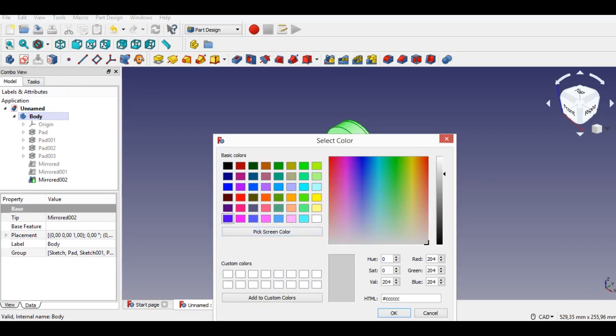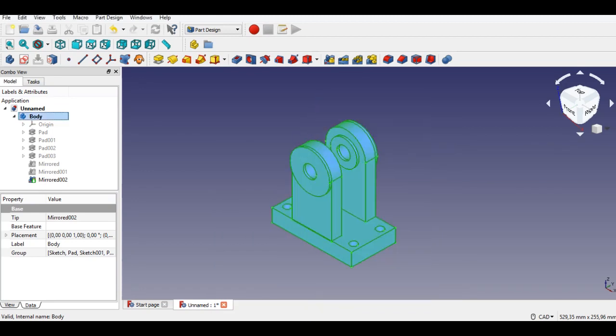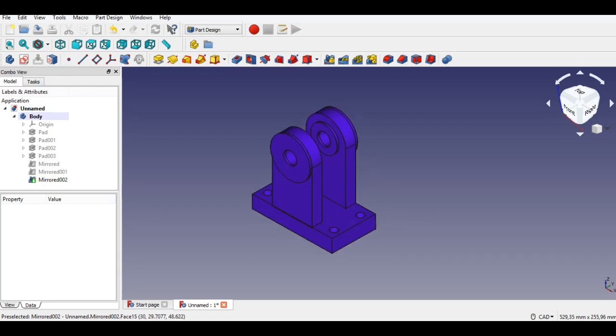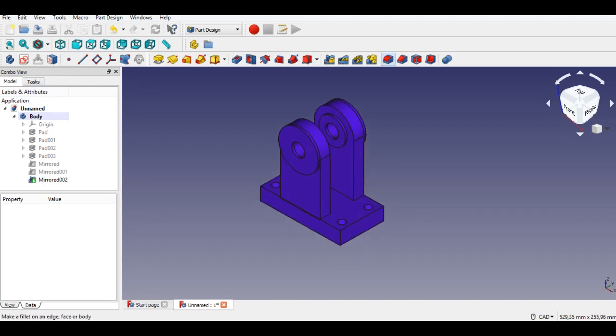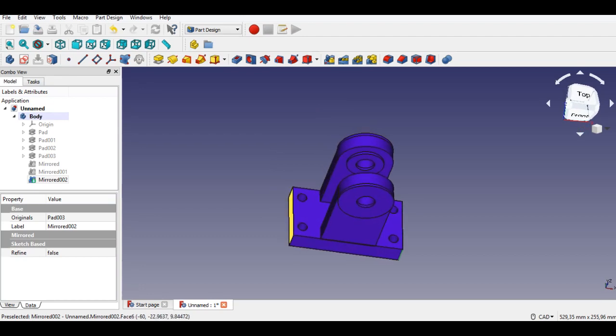Now we add a 5 mm corner radius. First we select the corners by pressing the Ctrl key, then click the radius command from the top. Part 1 drawing is completed. Open a new file for the saved parts. We save part 1 and we start our second assembly part.